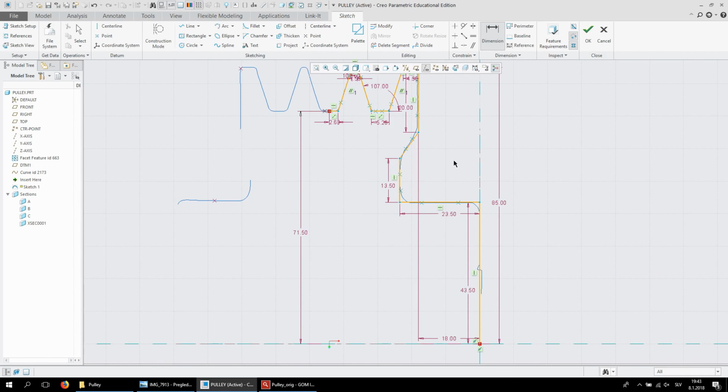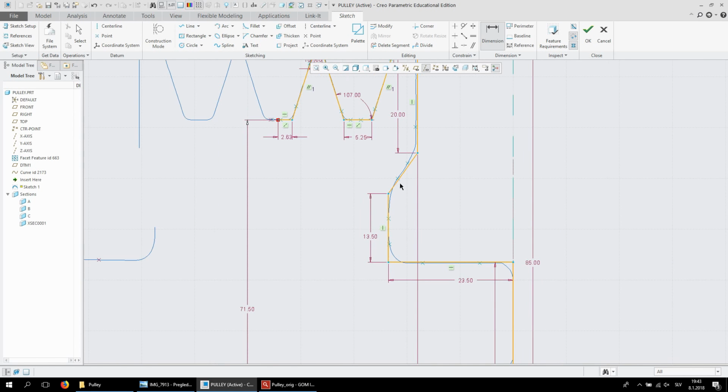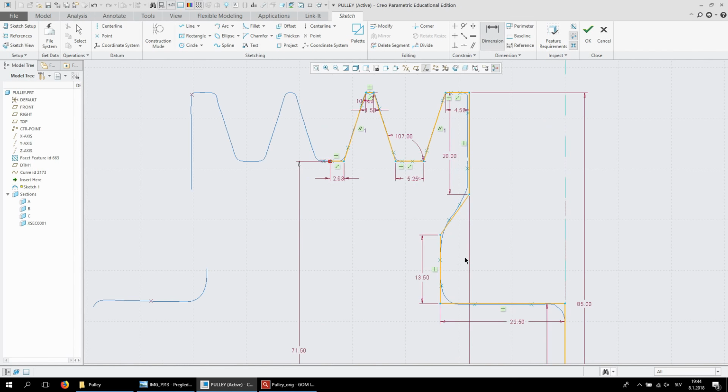Generally in any kind of modeling you try to avoid putting chamfers and fillets in the sketch, but in reverse engineering I sometimes use it because it's easier in the sketch to fit the lines to the curve, because you can see more easily how it fits. So I'm going to do this part here now in the sketch, but the others, here and up here, I'm going to do afterwards with rounds. So let's put fillets here,